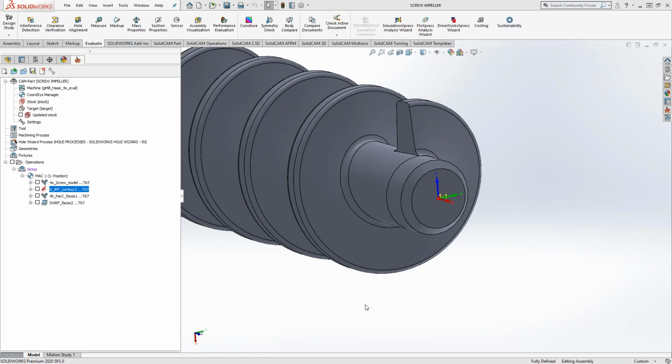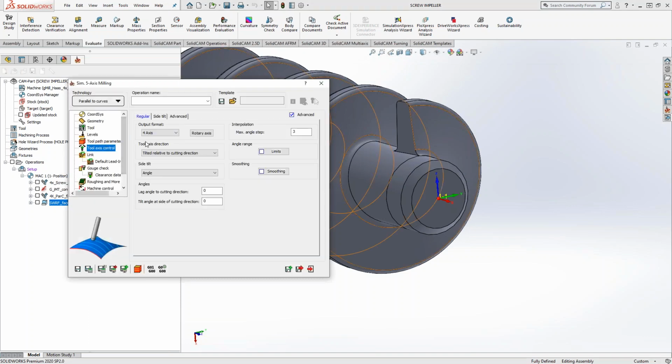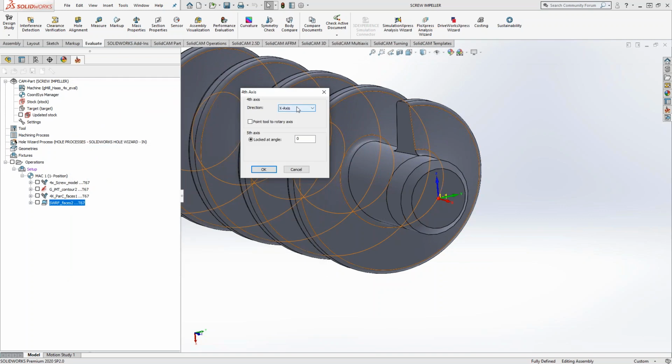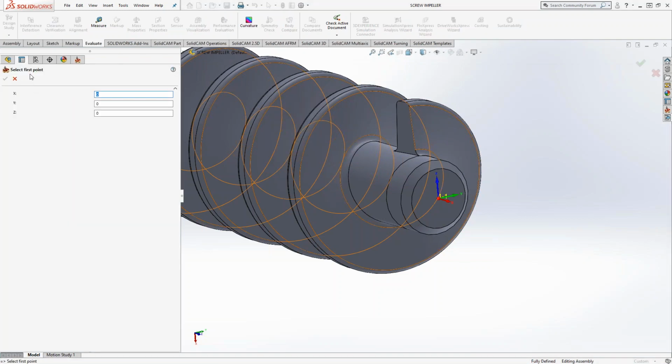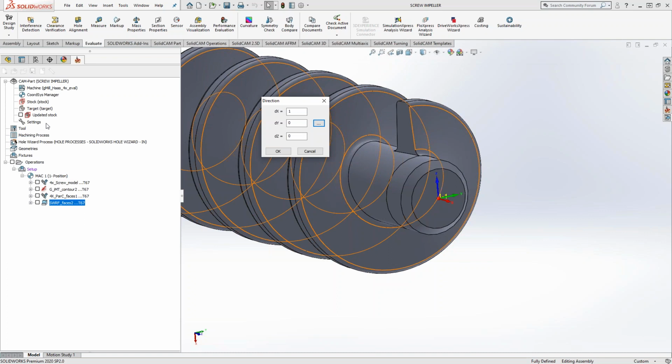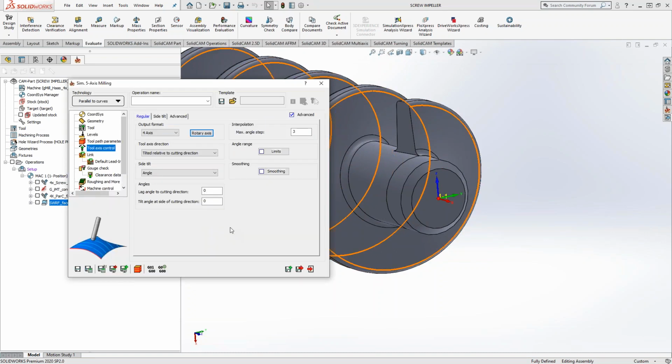If it's off center, or you've got some sort of embossment somewhere where you want to wrap around there, then you're talking about fourth axis simultaneous, and then you can choose your own axis. In this fourth axis simultaneous toolpath, we just go into that one real quick. It's called simultaneous 5-axis, but it's simultaneous fourth axis as well, because we can limit the travel of the tool. So we say fourth axis, under rotary, we can choose our own user defined. And then we just click on these 3 dots, and then you can actually define it by the first point, and then if I click on something, I'll get a second point. So I can actually define my own custom axis, and that gives me the ability to do wraps and stuff like that, but in simultaneous fourth axis. This is not the simple wrapped geometry that we're talking about here. So that's one limitation of this.